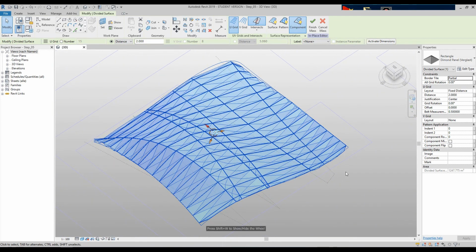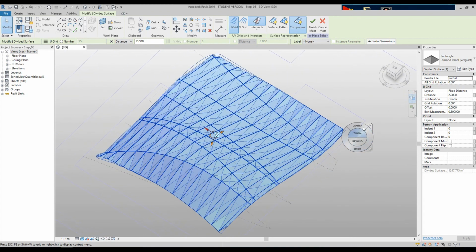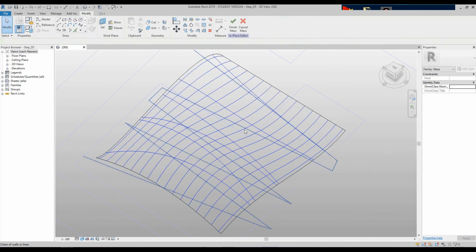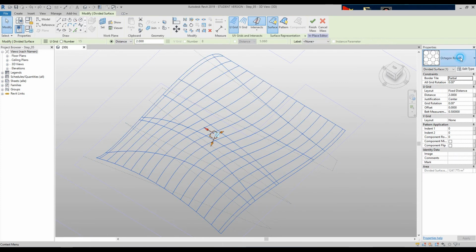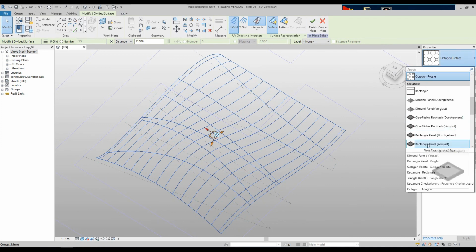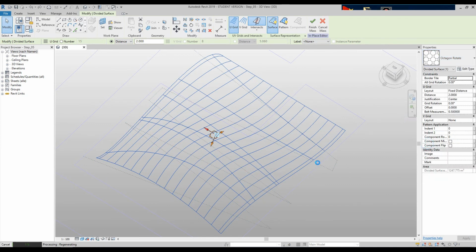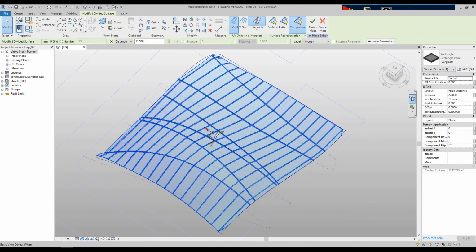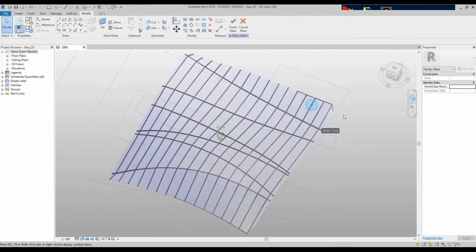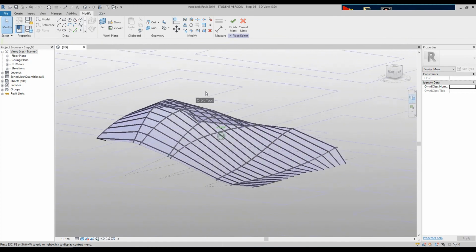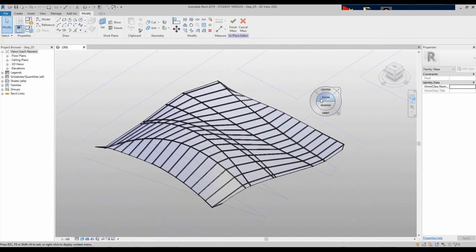However, that was just an example. We don't want that in here, we actually want the rectangular panel. So press Ctrl Z, so it goes back to a blank grid. Select the surface again. Now we'll choose rectangular panel. Again, it might take a while to load. Once loaded, if you click in negative space, you can see exactly what geometry has been formed.